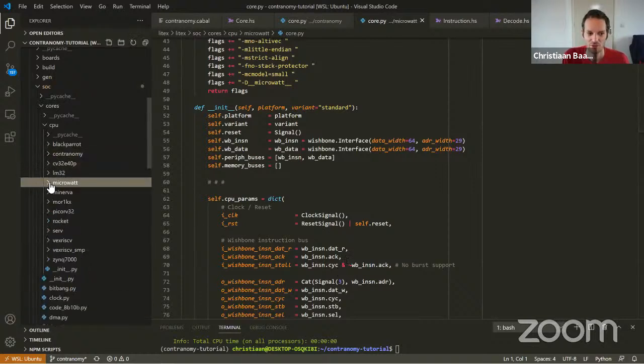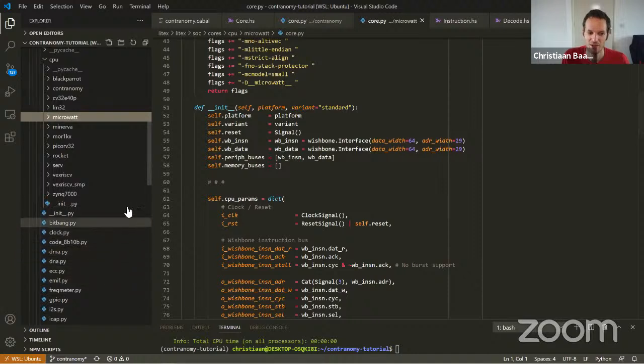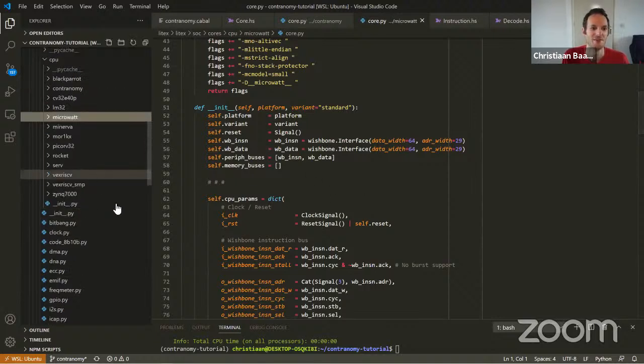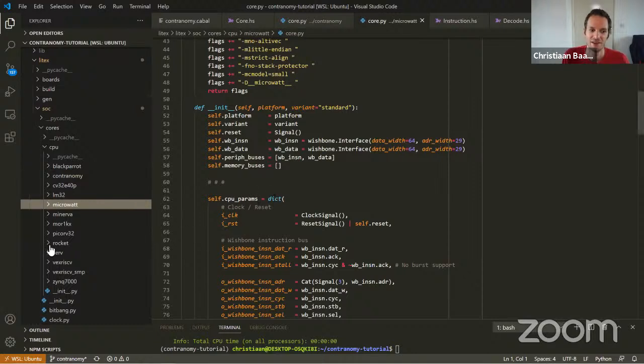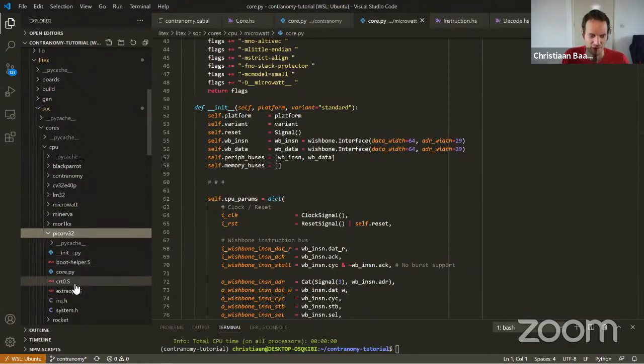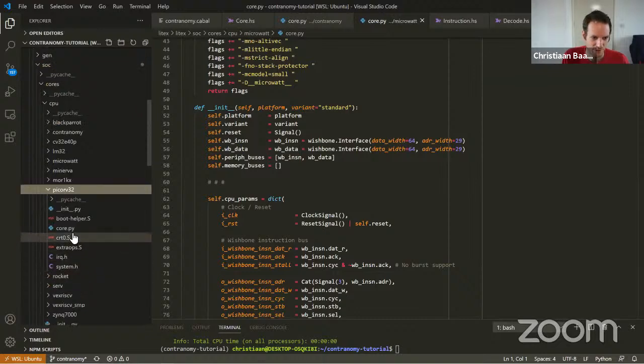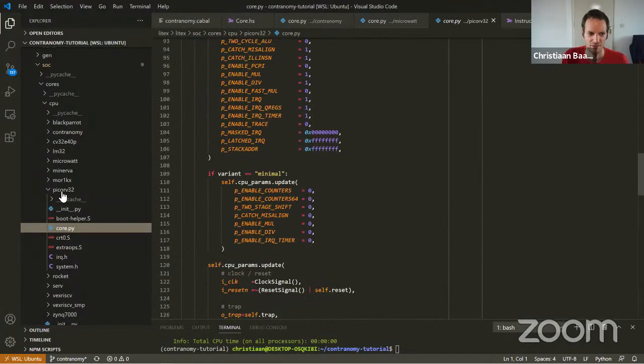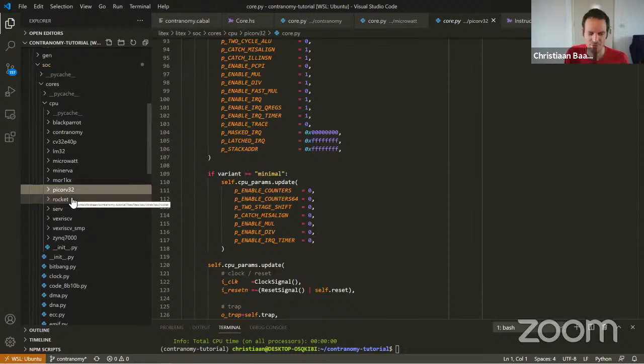If you want to go to these old school things, you'll have to implement a lot yourself still. But maybe it would be sufficient just to write an old school to Wishbone interface, and then you could go from there. Maybe the PicoRV32 one? I don't know, you would have to look. I think they are all either Wishbone or AXI4 buses that they use here, not something older than that.